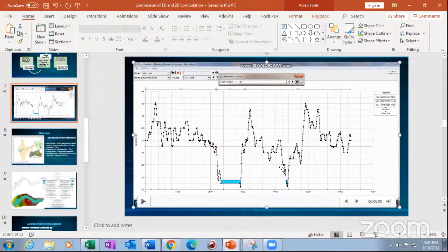Because if the cross section is at a certain level, it will account that volume also. Just imagine if this amount of volume is lost in this, then it will have a severe impact or severe analytical errors, right? That's why HEC-RAS 1D will have an issue when you're simulating it, but it has its own advantage when you have very good cross sections. But that is certainly not true in many cases in real watershed basins or river channels.